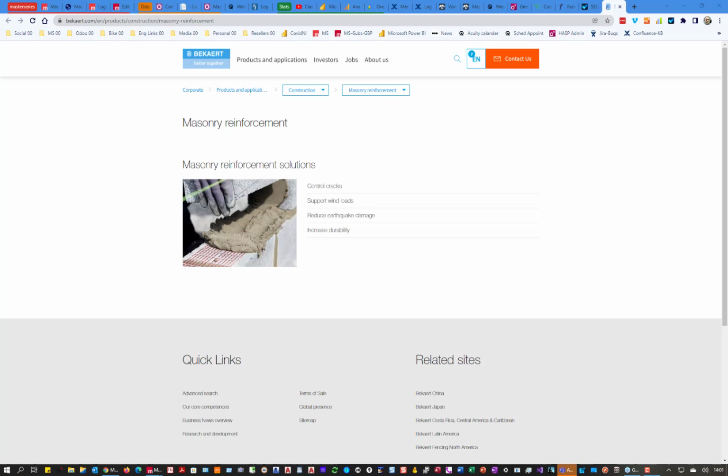How do you put leaf reinforcement at 75mm when the leaf is 215? Well, I could have used concrete bricks rather than concrete blocks, same thing, and I would have had to go back and say they're concrete bricks rather than concrete blocks. You're absolutely right, to go less than 215 is a wee bit onerous, but with the right shape of bricks, it's doable.